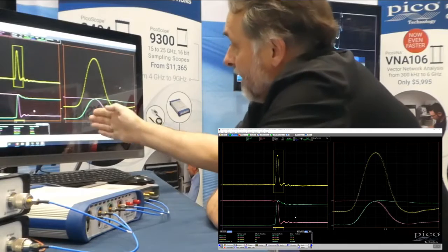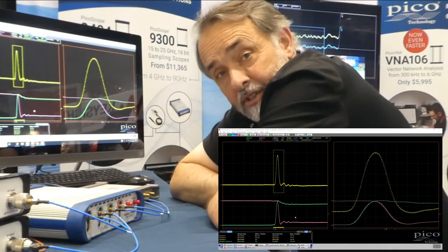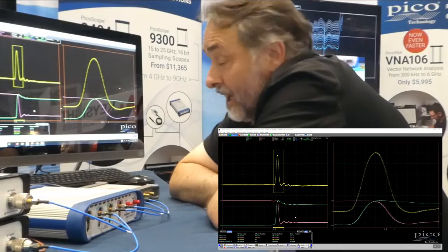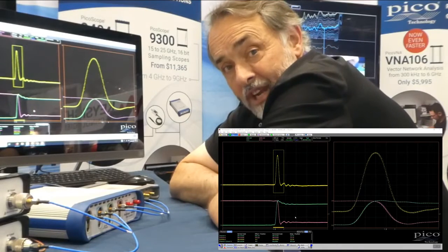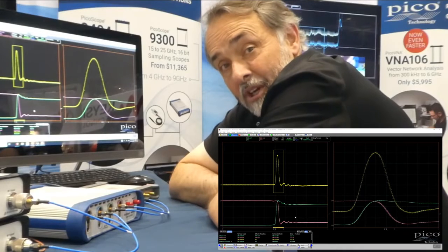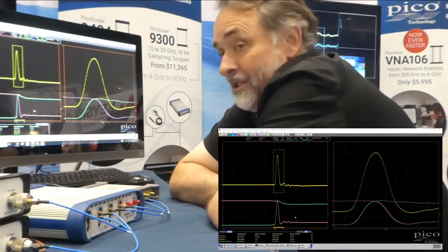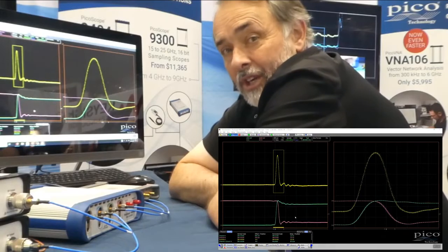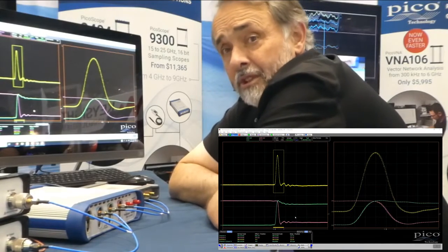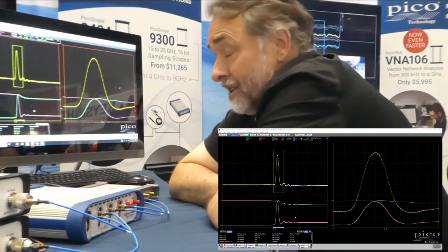What we're looking at there is 50 picoseconds per division. We're sampling that form at 1 tera sample per second, and as you can see, we're doing that with really quite low jitter. Jitter of the order of 1.5 picoseconds RMS, typical. Certainly should be less than 1.8 guaranteed.